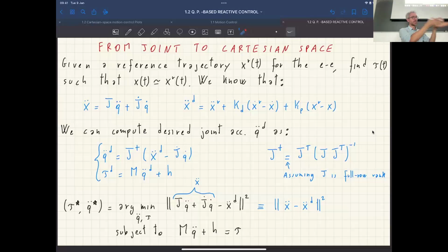And so you need to really use a camera to perceive the object position and orientation, and then plan, basically start moving. Doing that planning from Cartesian space to joint space and then the control in joint space is more complicated than doing directly the control in Cartesian space. So at that point, you would use Cartesian space control.